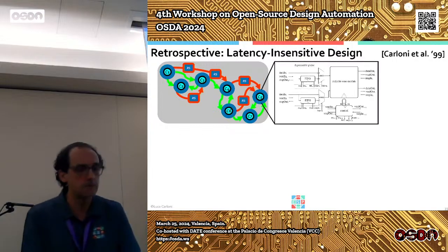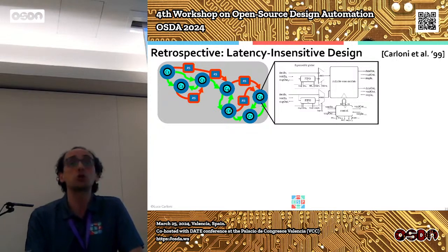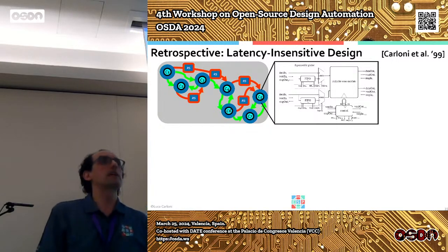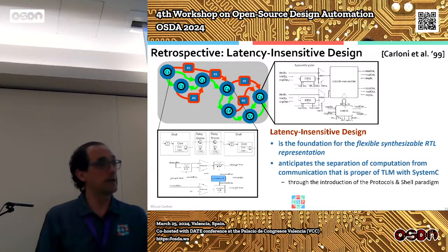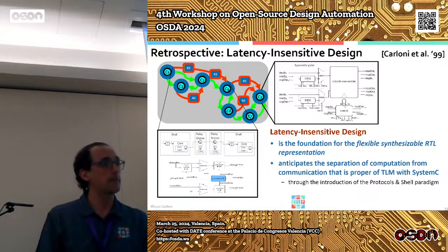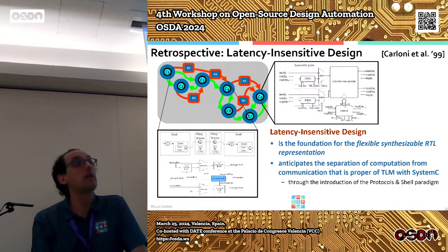This goes back to stuff that I've done during my PhD, which is the concept of latency-sensitive design, where at the time I was targeting the problem of long delay in communication between components on RTL design, so not with high-level synthesis. I created this theory of latency-sensitive design that tells you that if you take a piece of RTL and you decompose it in components that can be stalled through clock gating, then it's always possible for you to create a shell while knowing only the input and the output without knowing what the component does. And this shell, which is shown there around the stallable core, is really a combination of queues and some control logic for clock gating that allows you to pipeline the wires, and even if you change the latency on wires, even on feedback loops or very complex designs, you don't have to redesign the core. You are guaranteed to have a correct design. Your mileage for performance may vary depending on many system level considerations, but functional correctness, interpreted as latency equivalent design, is given by construction.